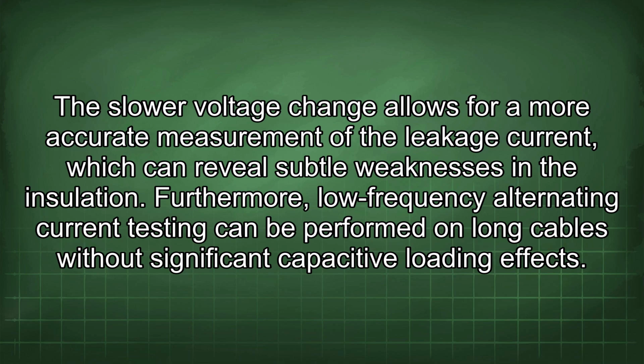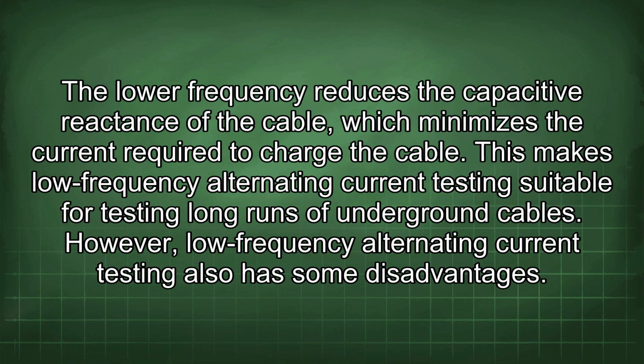the insulation. Furthermore, low-frequency alternating current testing can be performed on long cables without significant capacitive loading effect. The lower frequency reduces the capacitive reactance of the cable, which minimizes the current required to charge the cable. This makes low-frequency alternating current testing suitable for testing long runs of underground cables.